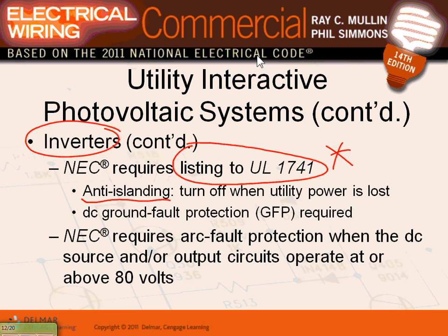What happens if you lose power and you're tied to the grid with the solar? Now the whole building, a 4,000 amp switchgear, 4,000 amp load at 480, is tied directly to the solar system that's only supposed to provide 1,000 amps, right? First you could burn your equipment, but there's a protection for this. The second thing, now you lost the power. If the power is lost, you want to be able to turn off the utility. If the power is lost, they want you to have a function to turn off your system because you're feeding into Xcel, guys.